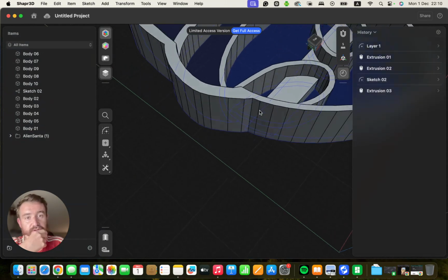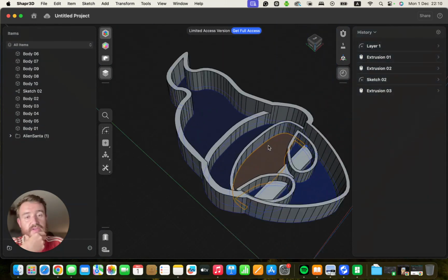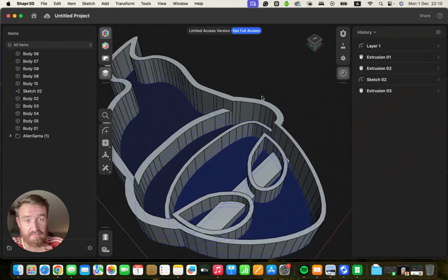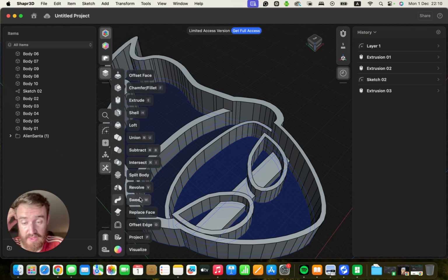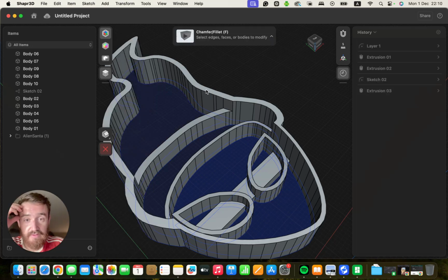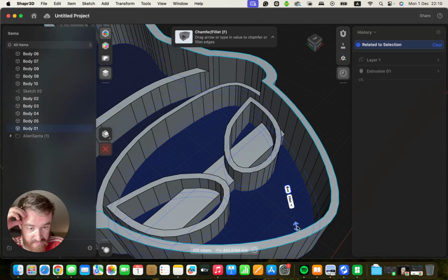So now we have all our details, all right? So the last thing would be, if we want to improve this mold a little bit, we can make a small adjustment here in the walls. We can add a fillet on the wall, so we can click this wall and then make this fillet.